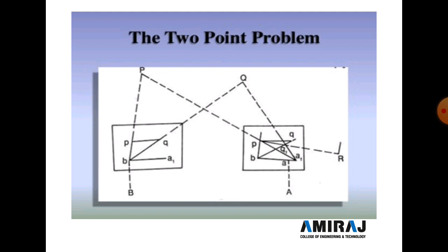First we mark the points A and B on the ground with wooden pegs. Then fix the plane table at point B. First leveling, then centering and orientation are required. From point B bisect point A and draw the line BA.